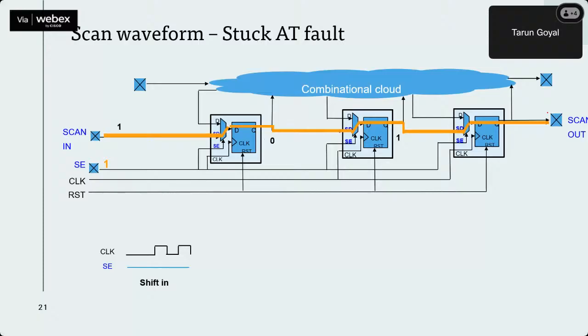Like this we are bringing the clock cycles. We can see 0 is there, scan enable 1, and then this went to the next clock 1, and this previous flop is loaded by 0, and in the next cycle this 0 went to the second flop, and then this previous one was shifted to here.